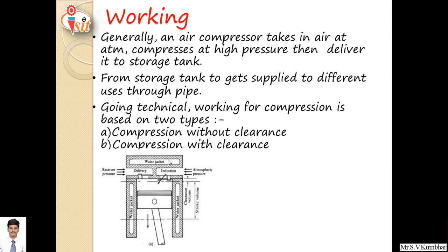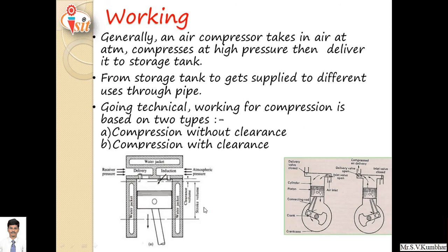These are the basic components of a reciprocating compressor. Here: delivery pressure, receiver pressure, atmospheric pressure, piston, cylinder, cooling system, water jacket, that is the cooling system, and stroke volume. The displacement of a reciprocating compressor is specified by its stroke volume, and the actual working is shown with the help of this figure.